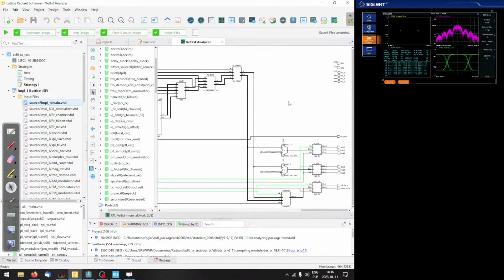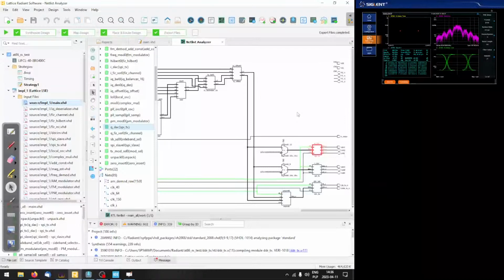All right. So what was wrong with the DAC? The DAC that we have used before. Actually, I'm not sure what happened at the DAC, because the signal there was really bad, and it didn't really look like the PSK. So I believe there was some glitch either at the DAC or in the VHDL code that handles the data transfer between FPGA and the DACs.